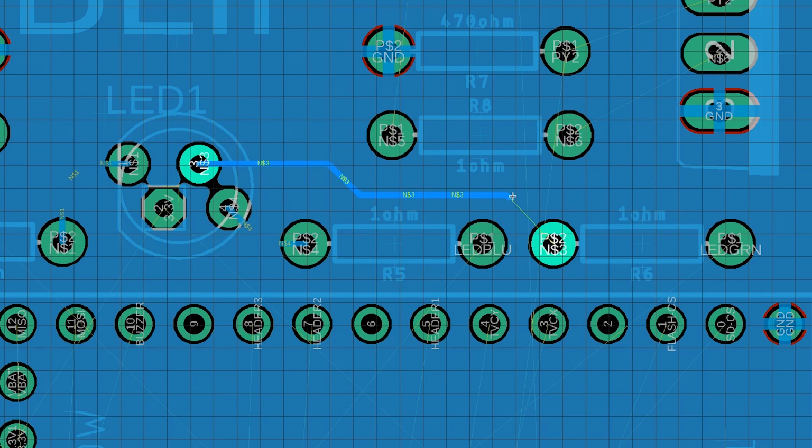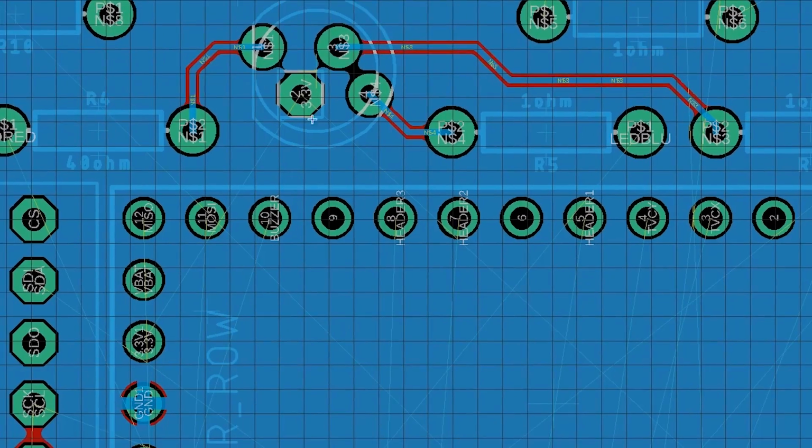You can see that PCB design is actually, I don't think it's that difficult. I'm going to go ahead and route as I talk. I don't think it's very difficult to do PCB design. I think it's mostly just tedious, because as your board gets smaller and smaller or more and more complex, instead of just being able to draw these traces, you start having to route around other objects. So let's say I want to take this 3.3 volt line and bring it over to this 3.3 volt pin, but the buzzer is now kind of blocked off, and the buzzer needs to go down, so you have to put a via through the board. All of these complex things start to happen once you route a lot of signals over the course of a whole board. Now, speaking of all this, I want to once again call attention to the flexibility of our design right now.